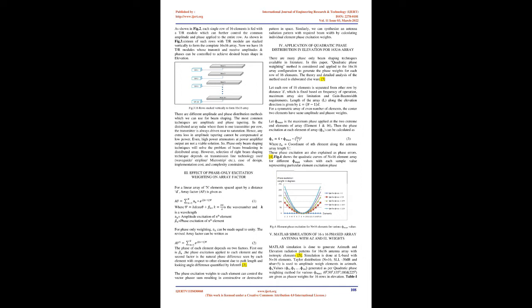2. Beam shaping approach for 16x16 phased array antenna. Consider a 16x16 phased array antenna arranged in rectangular fashion with 16 elements per row and 16 such rows placed one over the other in the vertical direction. Each row has 16 equally spaced elements, with each element fed through a 1-to-16 power divider, power combiner on receive, and element amplitude is tapered/weighted as per Taylor distribution, n equals 16, SLL 30 dB, NBAR 5, but all the elements are in the same phase as each other. This gives us a narrow beam in azimuth with a side lobe level of 30 dB.